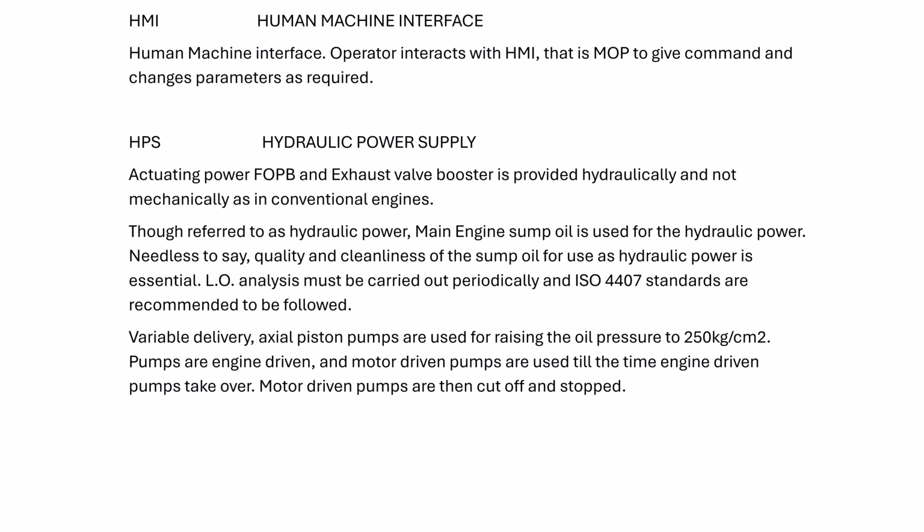For hydraulic power, variable delivery axial piston pumps are used for raising the oil pressure to 250 kg per square centimeter. The pumps are engine driven and motor driven. Of course, until the engine RPM is picked up, the motor driven pump runs; then the engine driven pump takes over and the motor driven pumps are cut off. All right. So this is about HPS, the hydraulic power supply.